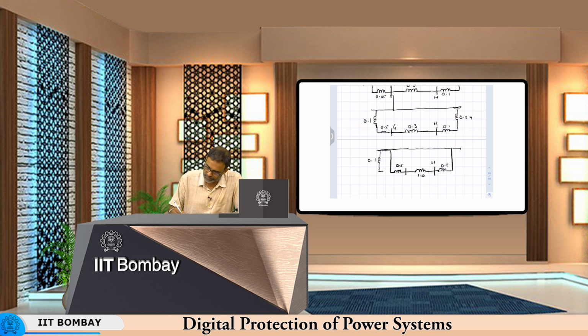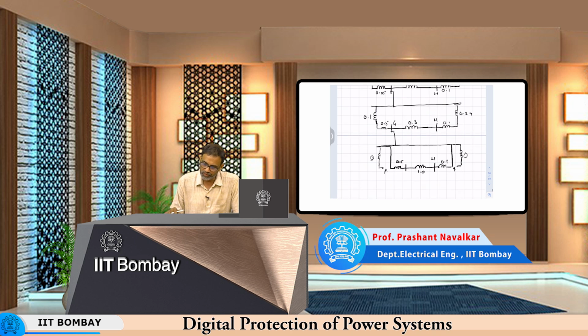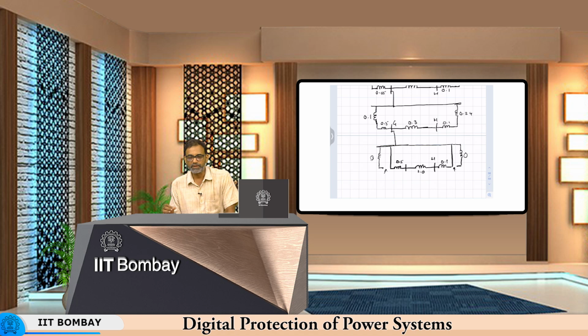One interesting thing is the zero sequence impedance of the source or the generator is not mentioned in our problem. I have mistakenly taken this as 0.1, but it is not mentioned, and nor does it matter in our case. Why? Because this is a delta star transformer, and zero sequence currents can't flow in the lines of the delta. So, these 2 points remain open. So, it is connected like this, and since they are open, the value of this or this does not matter. That is why even though the values are not given in the problem, they will not affect the results. Okay. So, we will stop here now, and we will continue with the calculations of this problem and another problem the next time. Thank you.